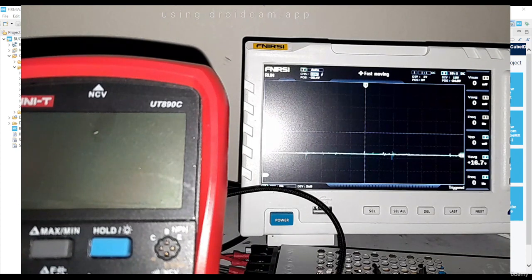For battery chargers, it's very useful, specifically in the bulk state. Of course, you cannot use average current mode control if you're not operating in continuous conduction mode. That would be a mess. If the inductor is not large enough, that's one thing to be cognizant of, that it is operating in CCM for the most part.